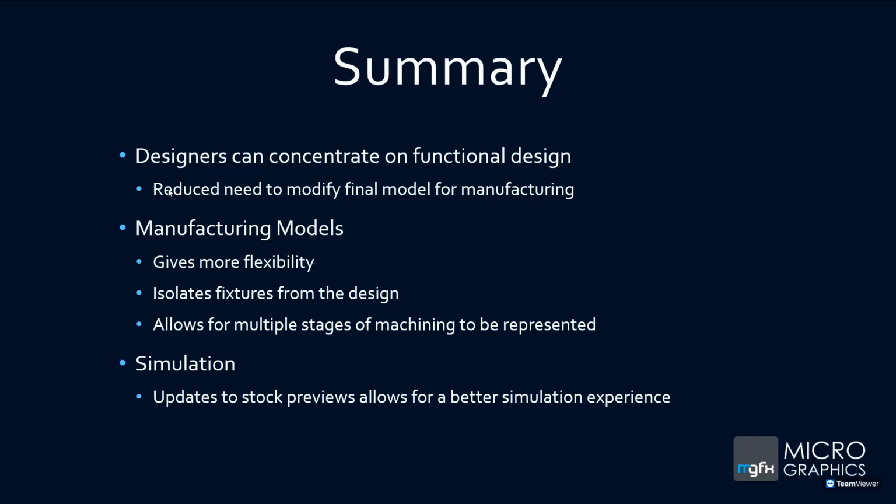And then just to jump on that last point of the simulation, the update to the stock previews allows for a better simulation experience. Being able to select a component and view the stock that is removed up to that point, including that operation, is very nice, and being able to start a simulation halfway through and have that stock removed is a very nice option.